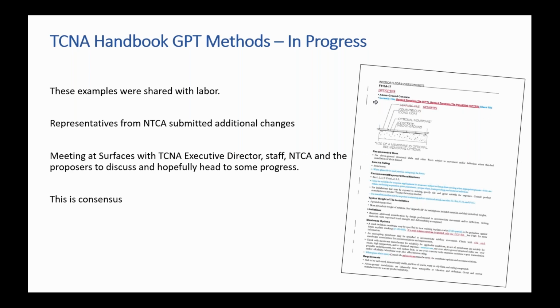Oh no, I'm sorry, this one has been corrected specific to gauge porcelain tile. So you'll see the ceramic tile and glass tile have been deleted, and service ratings are a little bit different. There are some specific requirements for GPT that won't be in the typical TCNA method. And so that's how you see this process starting to be done.